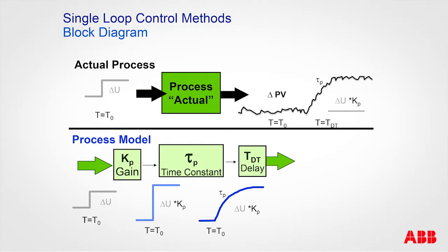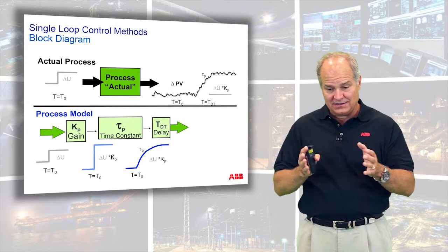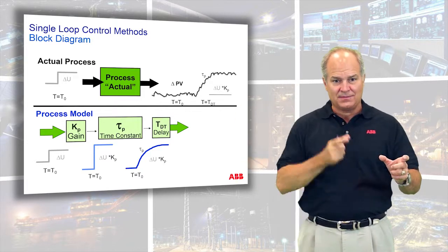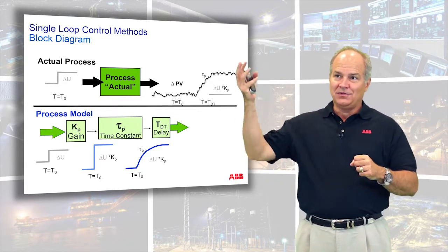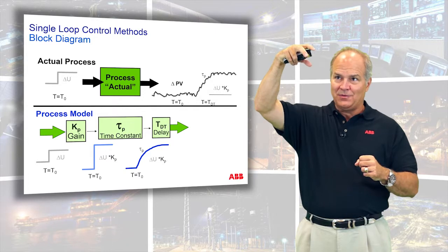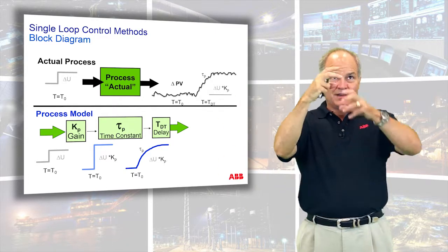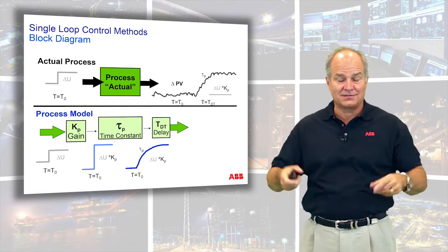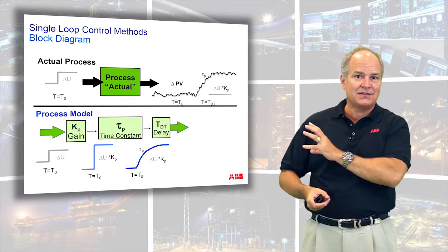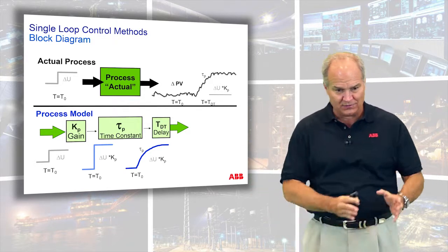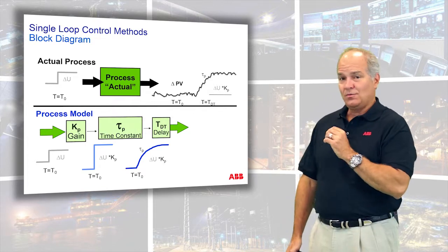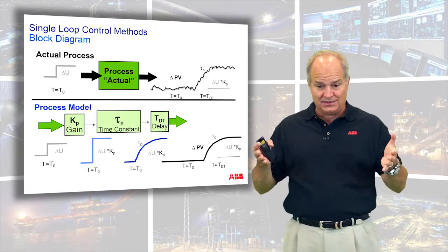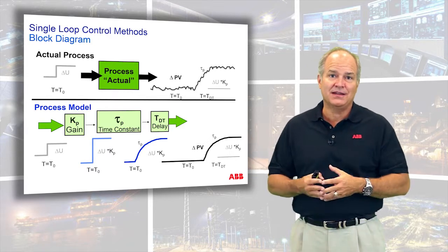Now what do you expect to come out? The only thing a delay does is, think of a Ferris wheel and all the buckets. Sometimes they call that a bucket brigade. We put something in one, and then it comes out. The amount of rotation is the dead time. That's sort of how my head works. But that's how these delays work: they shift buffer registers and out it comes. So what we should get is exactly what we put into it, only delayed by the amount of shifts, or the amount of dead time.